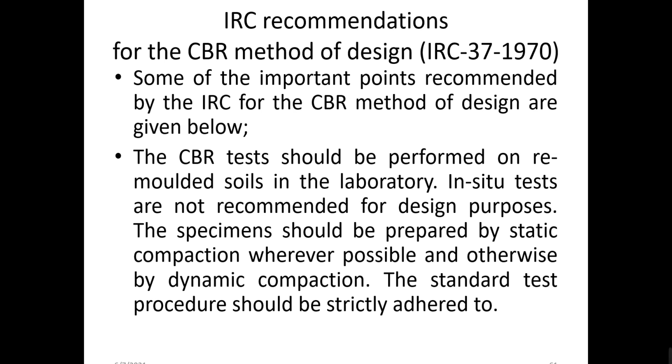It is not practically suited for recommending the design purpose. So what you should do is collect the soil sample to the laboratory itself for testing the CBR in terms of percentage. The specimens should be prepared by static compaction wherever possible, and otherwise by dynamic compaction. You know what you mean by static and dynamic. Again, you should not repeat it.